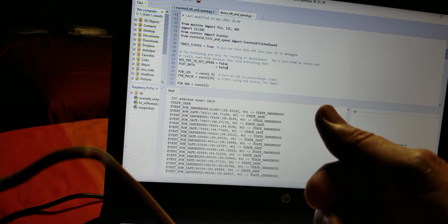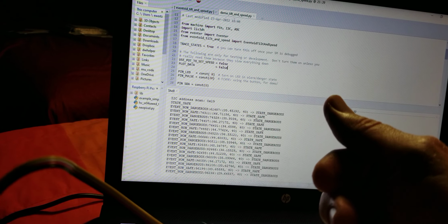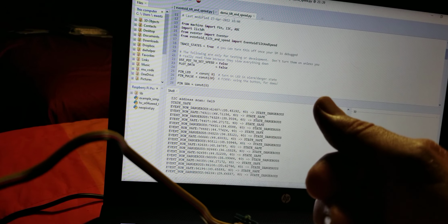You'll have to replace all the fake math. You'll have to do real speed computation. So you're going to want to time the difference between pulses in the interrupt handler. And there's actually a little bit of sample code in there to get you started on where and how to do that, but I don't do it for you. So you're going to change the interrupt handler to take my notion of fake speed and change it to a real notion of speed. So that's for you to do.